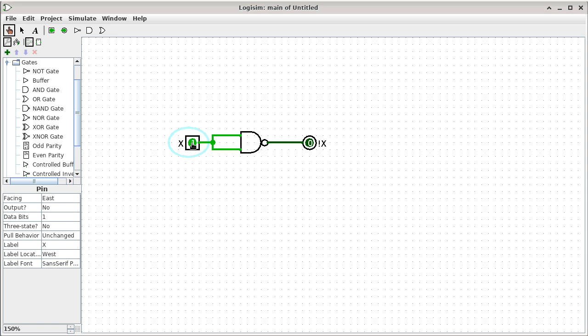So do they know, on average, they need this amount of AND gates and this amount of OR gates? The translation from gates like AND, OR, NOT, NOR, NAND, and so on, to actual transistors is done by what we call a silicon compiler. So it's not even done by hand, it is done by a compiler. The compiler looks at the description of the circuit, how the AND, OR, NOT, NAND, and NOR gates are connected, and figures out the optimal way to implement the whole thing in transistors.